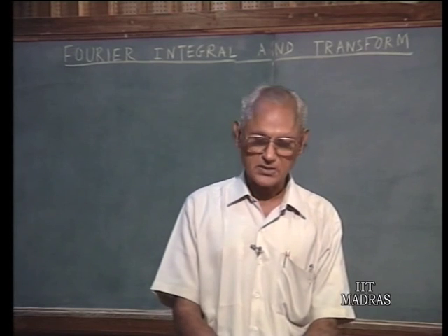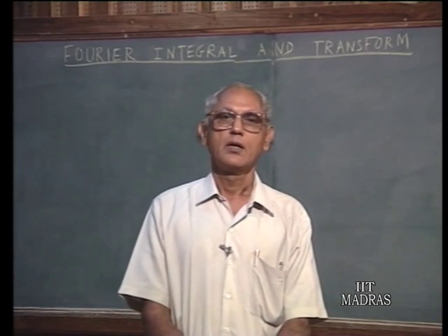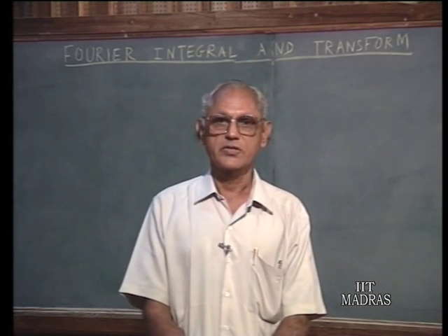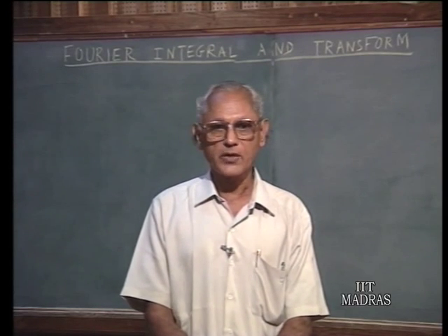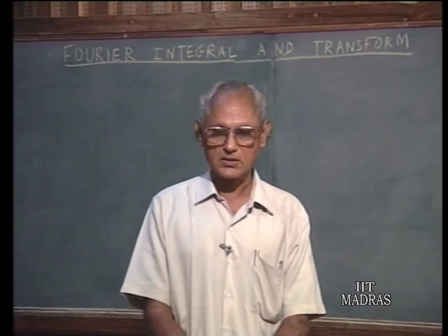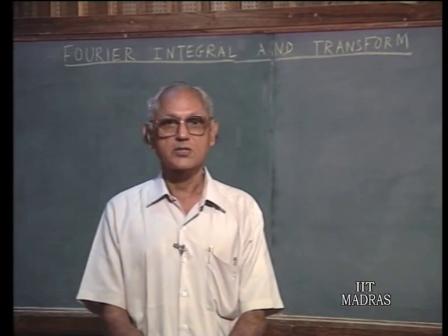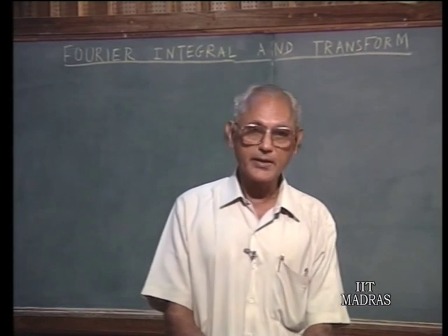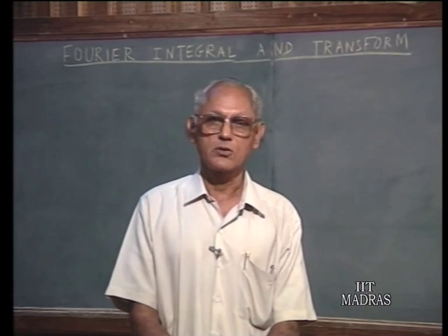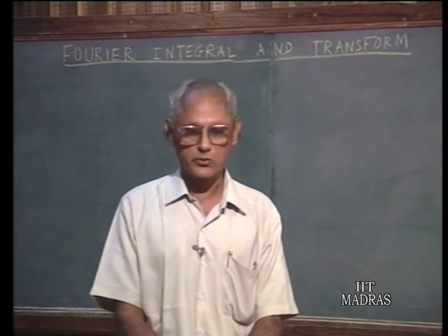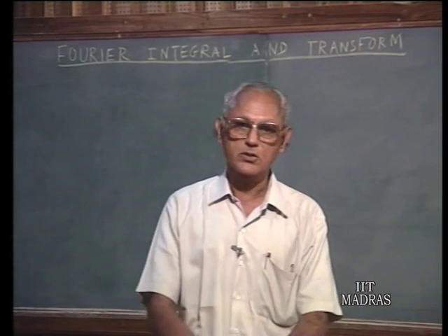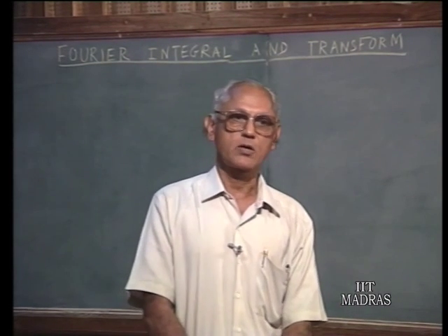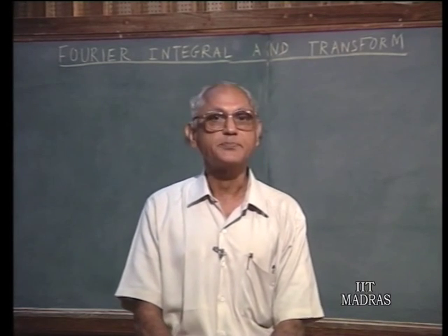Under these assumptions, when we have an excitation switched in at t equals 0, we expect the response also to be 0 for t up to t equals 0, because the network is assumed to be causal, and therefore, any excitation that is applied at t equals 0 cannot produce a response prior to that. So, we expect the response to be 0 up to t equals 0 and then become non-zero from t equals 0 onwards for positive t.